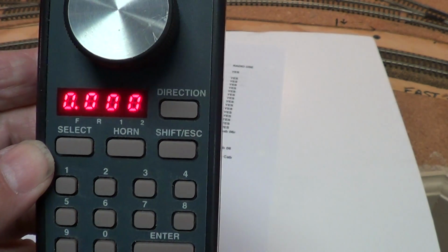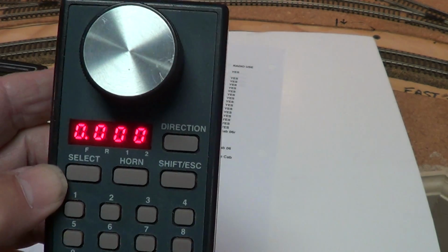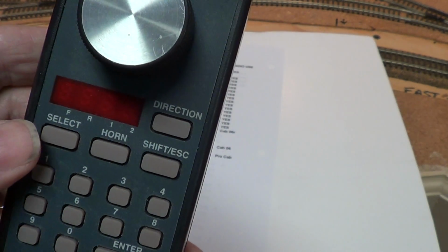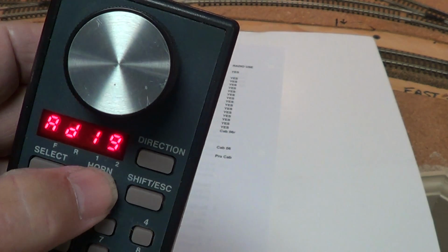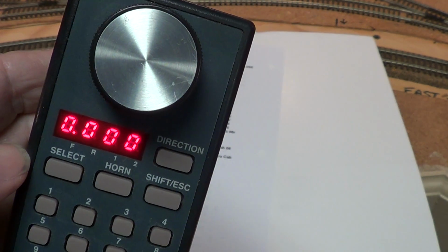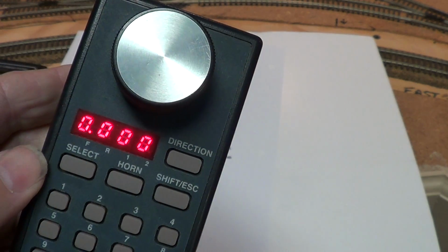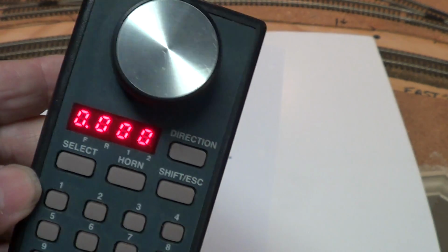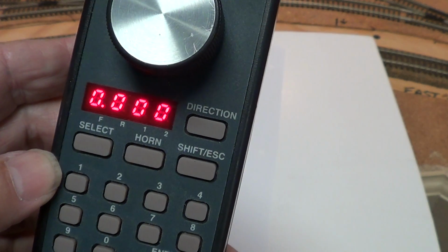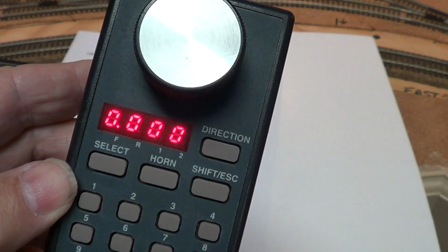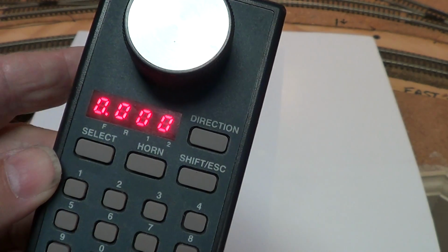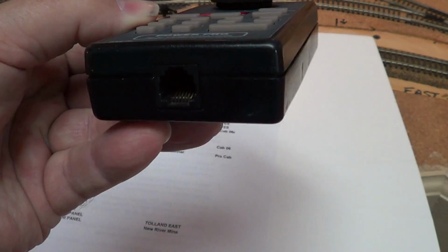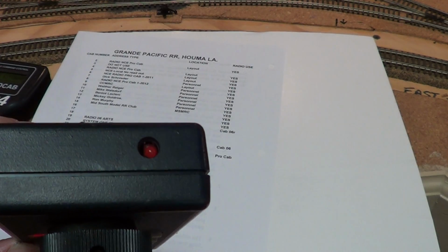So that's how you change the address. You got to hold the select loco key, and it's got to be done here. So we'll unplug that. On a cab 06 to turn it on, you just hit the horn button, and there you see it came up cab 19, and then it went to the loco number, and we had cleared out the other one, and now it's coming up 0, which is where we want them to come up. Strongly recommend that you select loco 0 whenever you finish with a cab. That way you don't have plug in, turn knob, and have some loco take off down the track. So that's just that simple for a cab 06.